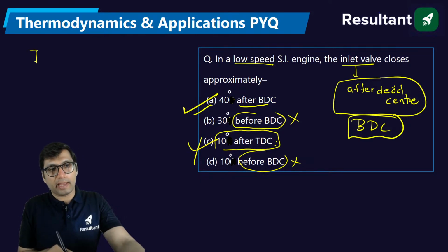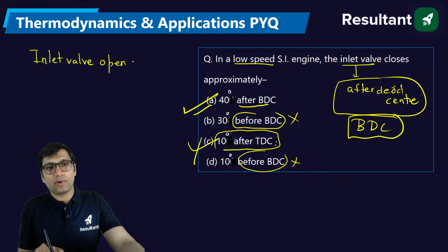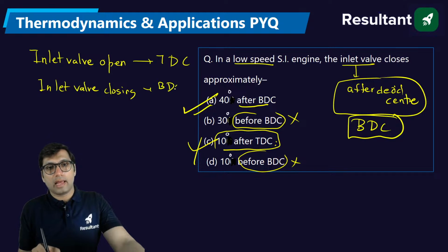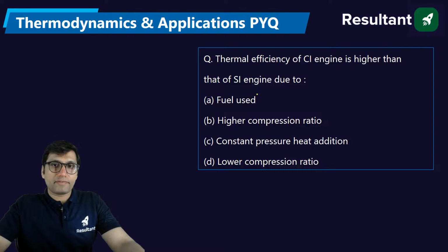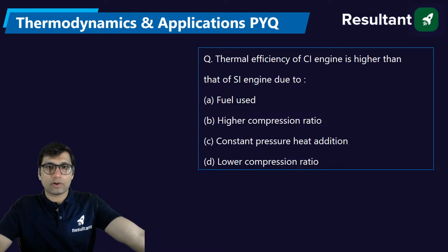The opening of the inlet valve is with respect to top dead center, and the closing of the inlet valve is with respect to bottom dead center. So if it is an actual engine, it will only happen after dead center, so after bottom dead center. Okay.